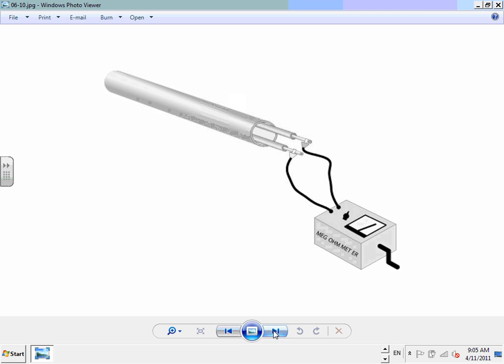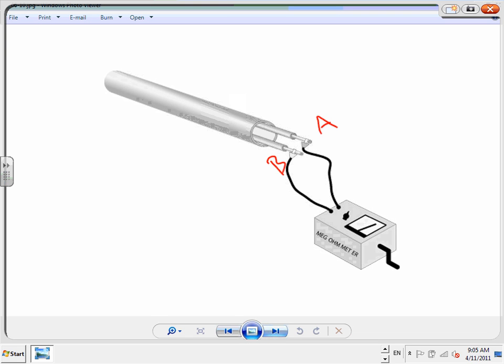Look at that. They grab phase A, really cool, phase A and phase B. And they send the signal through phase A and phase B. And Spencer, you know what they're looking for? They're looking for short circuit. If the impedance between phase A and phase B shows infinite, huge amount, this means the insulation is 100% perfect. But suppose inside this conduit, right in here, it's shorted, right? The 2 phases are shorted. Because when you pull them, you damage the insulation.